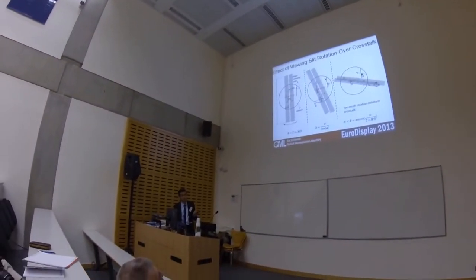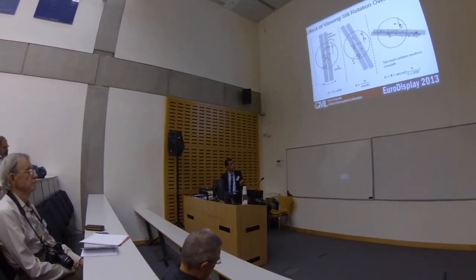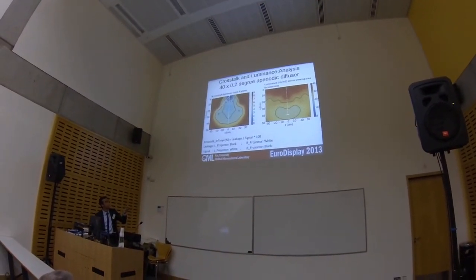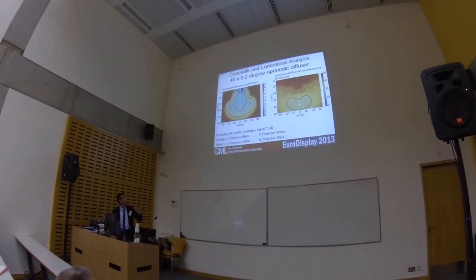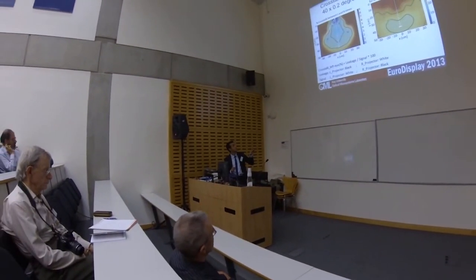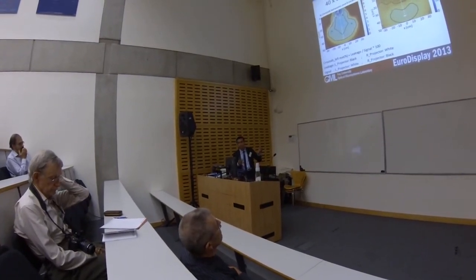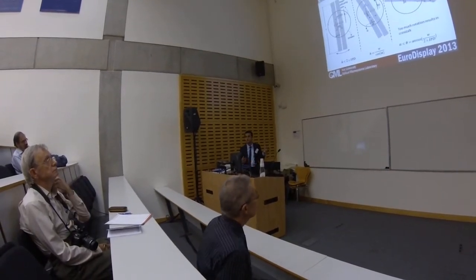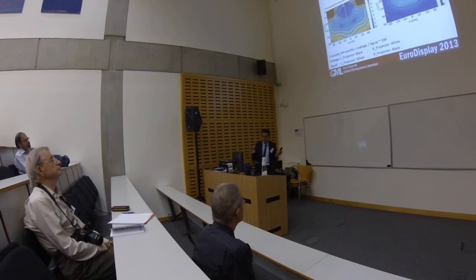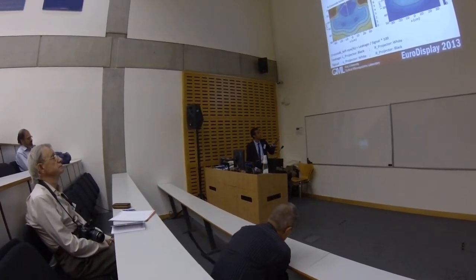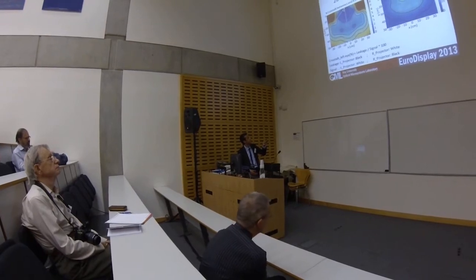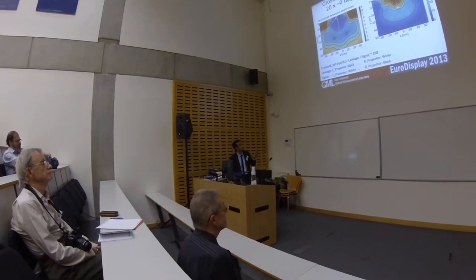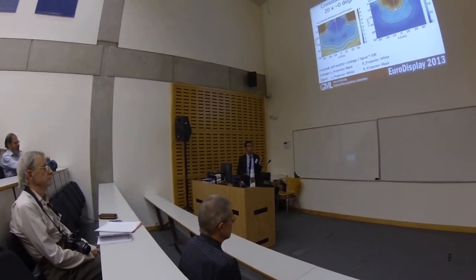So to reduce the crosstalk, we need to reduce omega. How do we reduce omega? I have said there is a 0.2 degree diffusing angle in one direction, so we must reduce this diffusing angle. We used another diffuser that we took out from a regular laptop screen, and it has almost 0 degree diffusing angle. It's a periodic diffuser, 20 by 0 degree, and we also analyzed its crosstalk and luminance values.